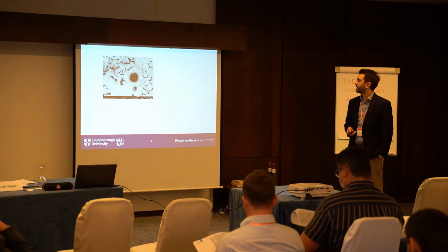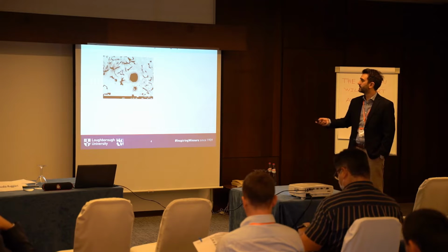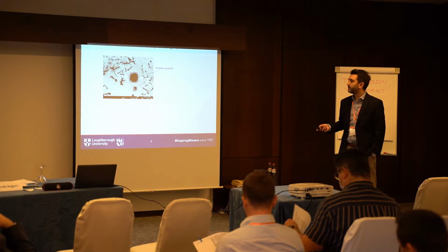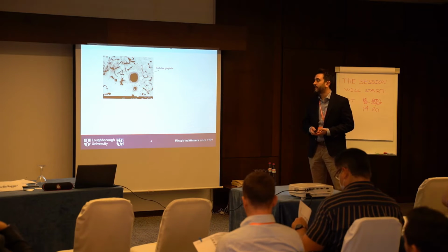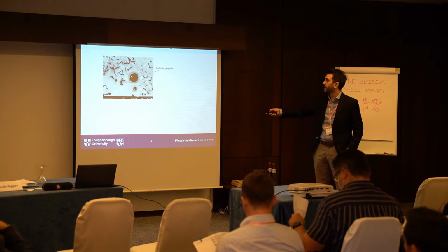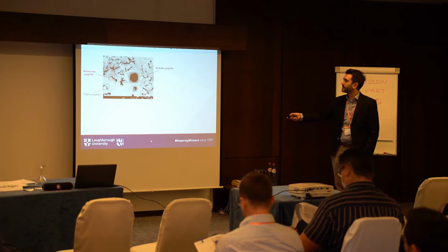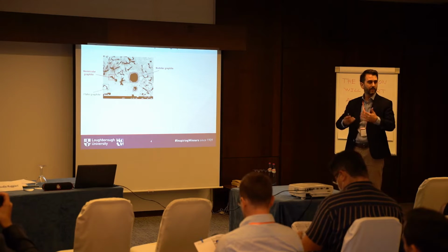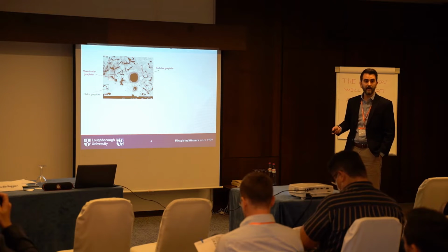Back to the material science and the mechanics. Why is this material interesting? What is interesting is its microstructure. This is a typical micrograph, and what you see here is a combination of primarily ferritic matrix and some graphite. Based on the shape of these graphitic inclusions, we can distinguish a circular shape called nodular graphite, then a shape looking like a worm or a sausage, vermicular graphite, and then flakes, like pieces of paper, flake graphite. This is what you find in the compacted graphite iron.